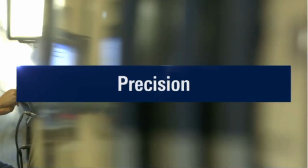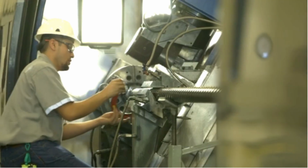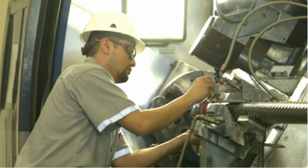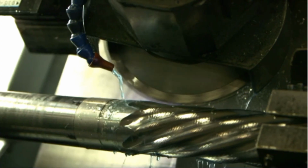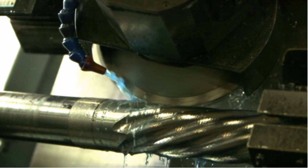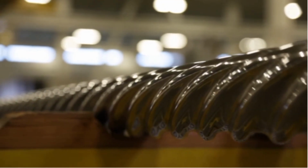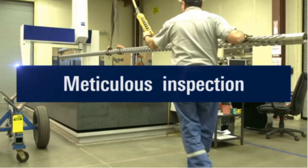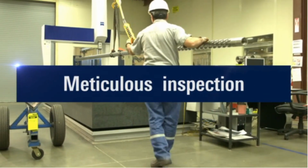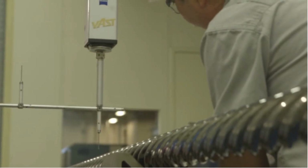Dynadrill rotors are produced through high-precision computer numerical control CNC machining. We maintain the industry's latest and most sophisticated milling equipment to precisely contour rotors of various lengths. After machining, the rotors are carbide-coated or chrome-plated to maximize protection against wear and erosion. Dynadrill verifies every rotor profile using a coordinate measuring machine, CMM, and proprietary contour measurement software.